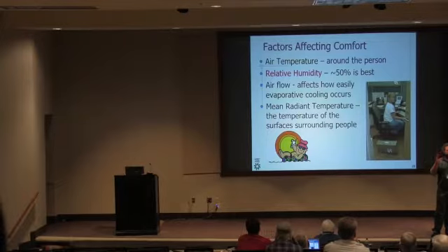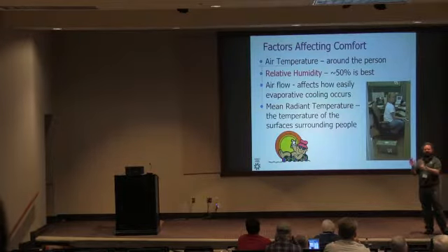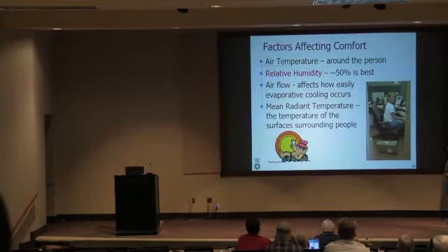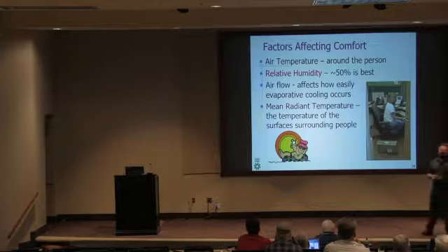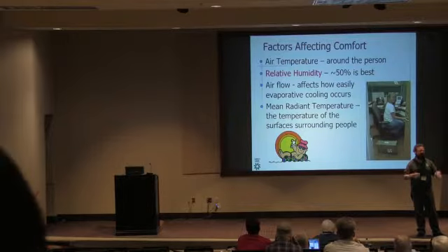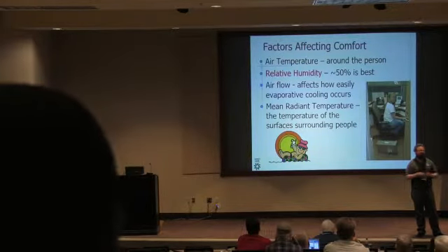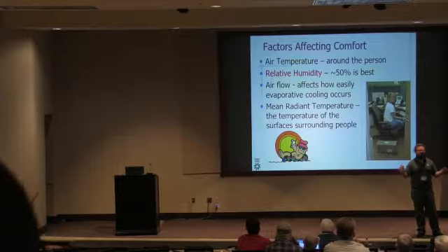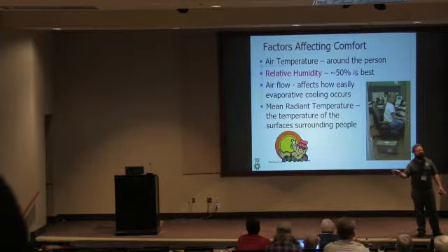A mass wall is a big storage bank for thermal energy. Those surfaces stay cool even when the temperature outside gets warmer, and they have big thermal lag. The air temperature is not that much cooler, but the surface temperature is dramatically cooler, and your body radiates heat to the cooler surface, right?